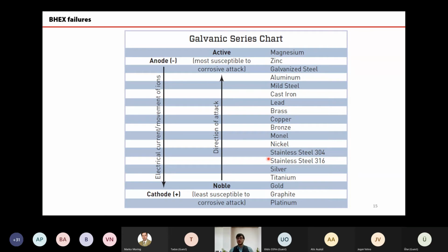Because high electrical conductivity simply means the presence of a lot of different chemicals in the water, because the pure water itself, H2O, doesn't conduct electricity because it doesn't have any ions to conduct electricity. But as long as we have any additional chemical parts in this water, it becomes conductive. The more conductive it becomes, the faster copper will be eaten away. And of course, the faster the copper is eaten away, the faster the failure will happen.